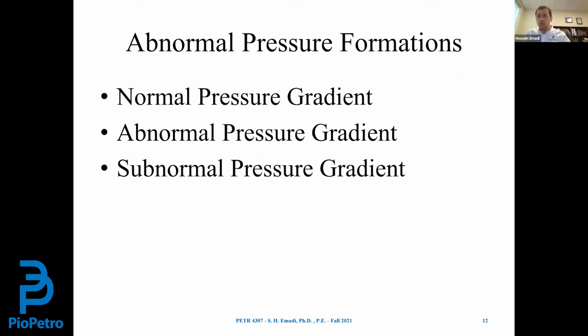Is it good or bad? During drilling operations, we don't want to see any abnormal pressure formation. Why? Because they are troublesome and they may lead to issues like kick or blowout.